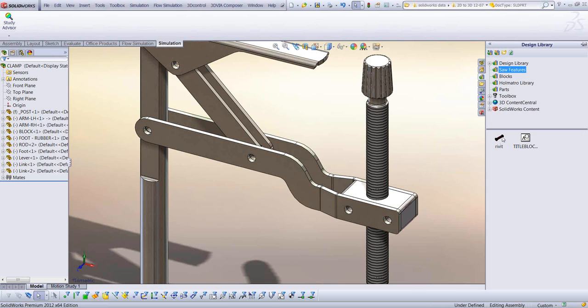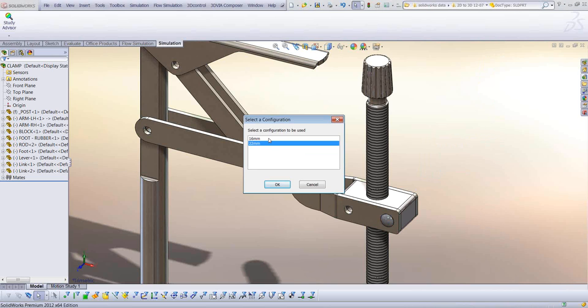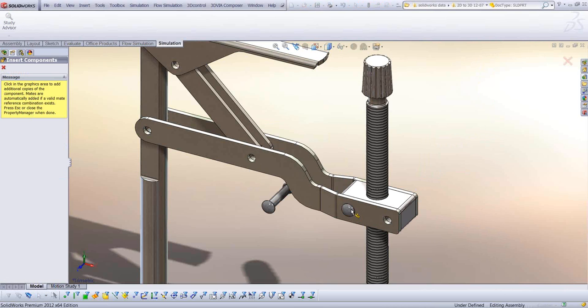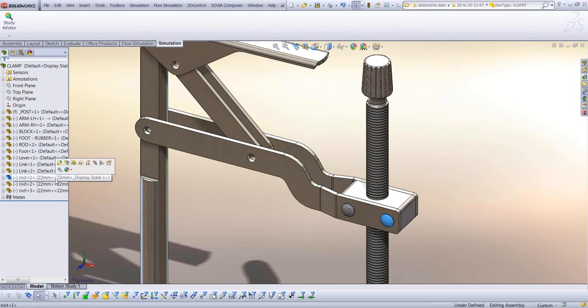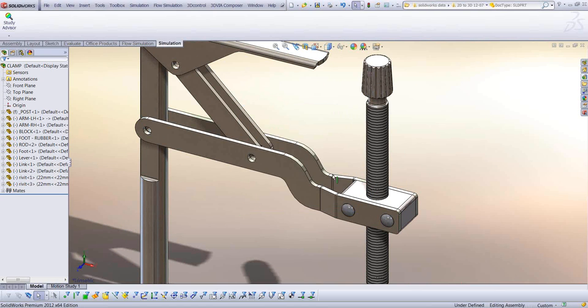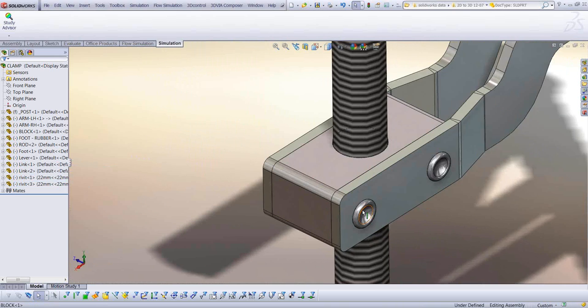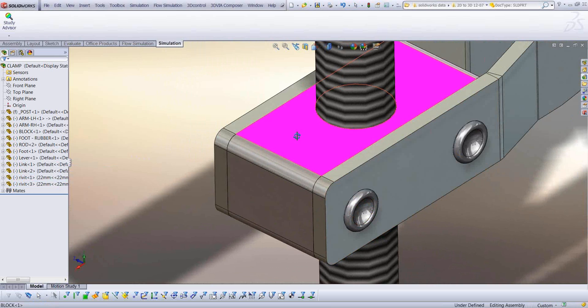So as soon as I drag and drop this onto the user interface, SolidWorks will ask me the length. So for this, I need a 22 millimeters. So I'll just quickly say OK. And let me place it. So we have 2 rivets added now of the appropriate length, 22 millimeters, and you didn't have to add any mates at all.